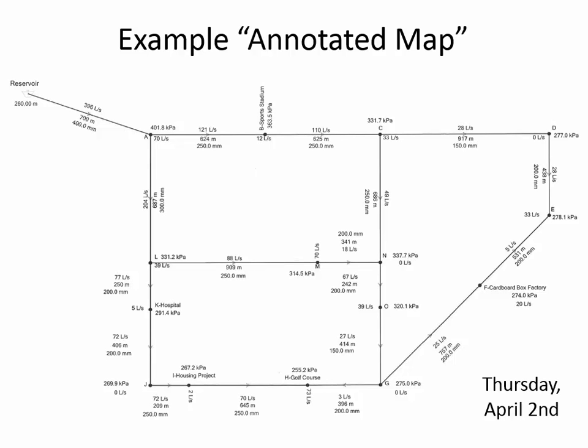That's optimization, is go save your client money by making the pipe smaller until the pressure, ideally you'd have 241 kPa at every junction. But you can't really achieve that because there's increments of pipe sizes. You're not going to be able to put in a 203 millimeter diameter pipe because they don't make a 203 millimeter diameter pipe. They make 200, 225, 250. I think I marked the pipe sizes on the handout.